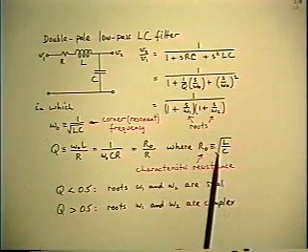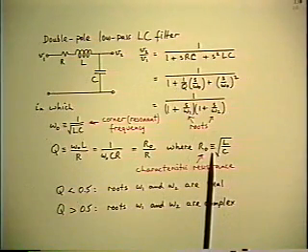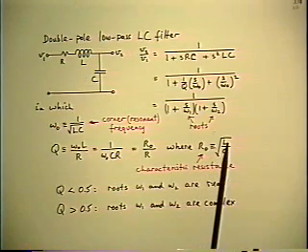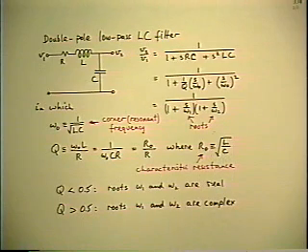I never understood why it was called impedance when it's really a resistance. But I didn't choose the name for transmission lines, but I've taken the liberty of choosing the name when it's a lumped transmission line, where you have a lumped L and C, and the characteristic resistance is root lumped L over lumped C, and it is a resistance.